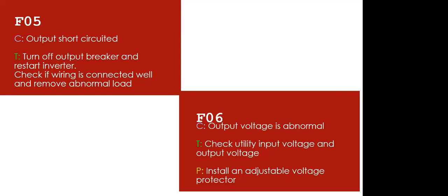At times, F05 will come as a warning. If you notice it in time, you restart and you check what is supposed to be checked. Maybe your load: you turn off all the load, all the breakers connected to the output, and you turn off the input connected to it, because it may come in either way. The output cable might short circuit with the input cable. It is still a short circuit because it will be seen as feedback.